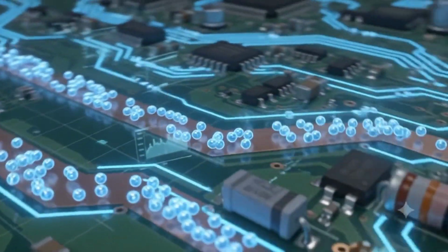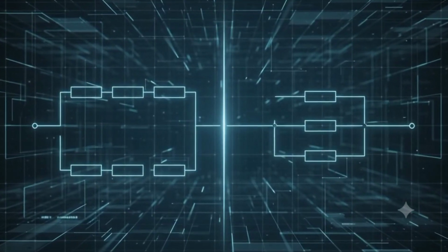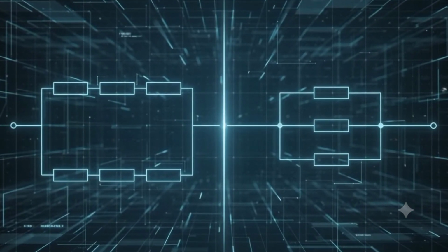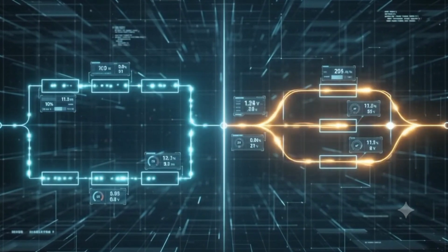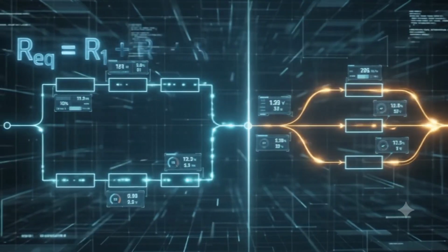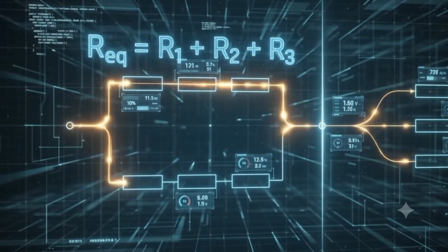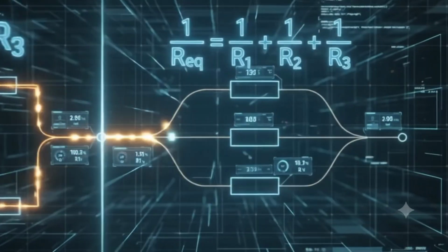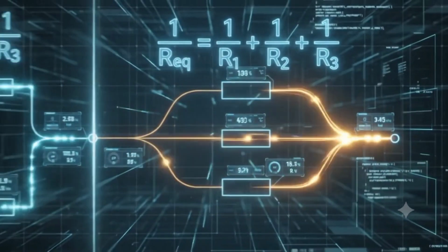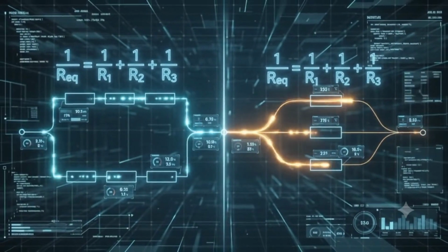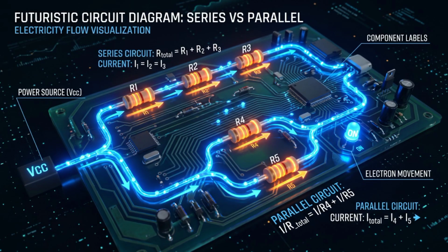If resistors are connected in series, their values add up. If they are in parallel, the total resistance becomes smaller. So if you measure a resistor in a circuit and get a strange value, it's not broken. It's just sharing current with other components. A 10K resistor might look like 3.3K ohms because other resistors are connected in parallel. This is how engineers think, not just measure.